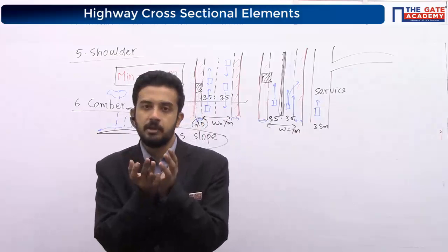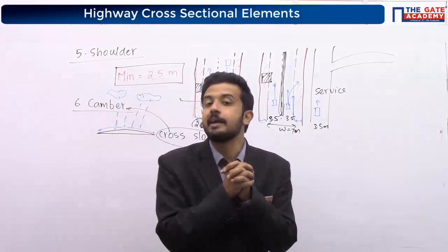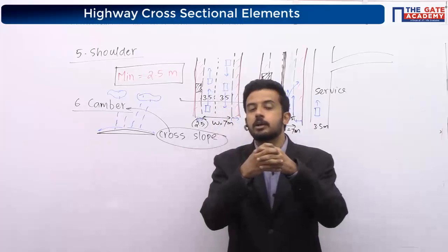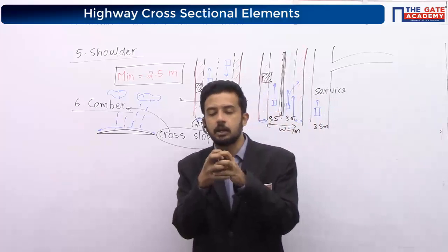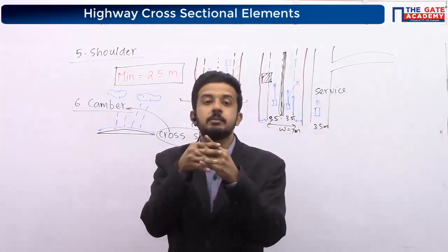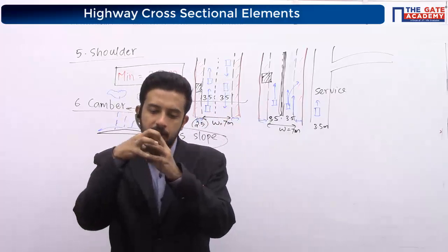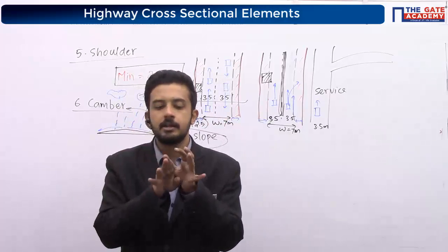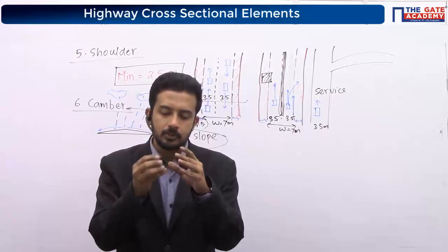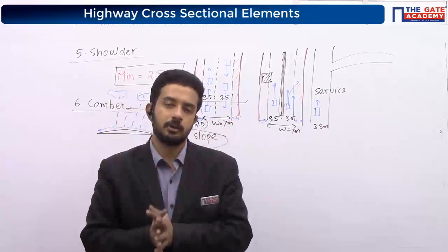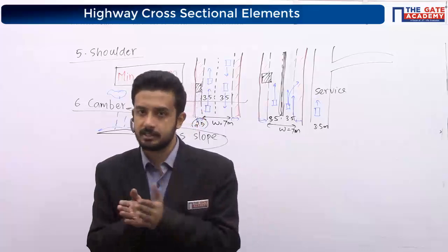For a flexible pavement, the strength highly depends on the interlocking between the aggregates, and the cohesion and adhesion between the particles. So whenever water intrudes into that, it will affect the bonding. So the particles will come out. We call it segregation sometimes.